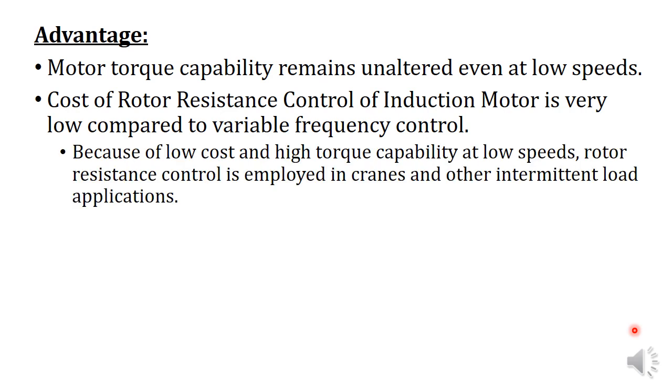So, because of the low cost and high torque capability at low speeds, rotor resistance control is employed in cranes and other intermittent load applications. It's a very popular method.